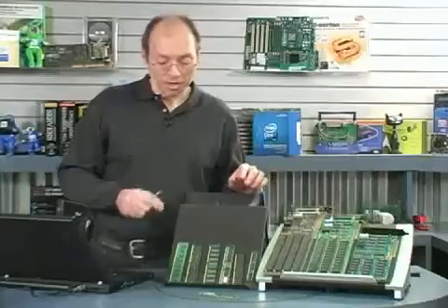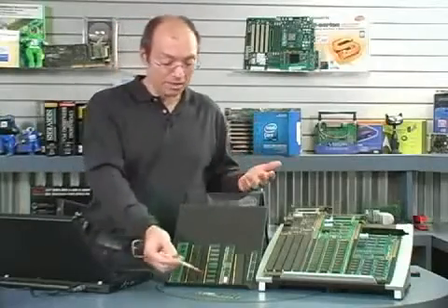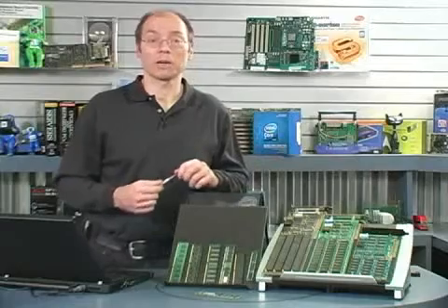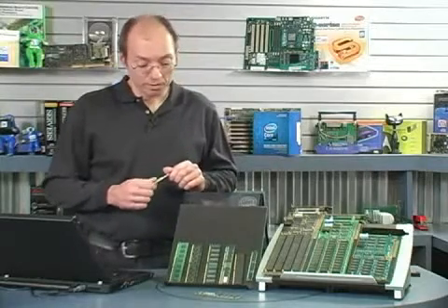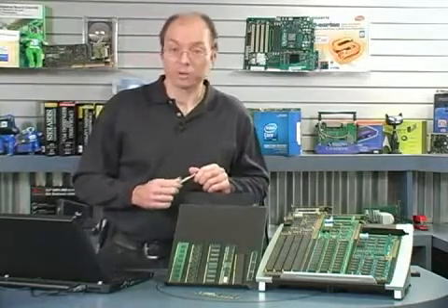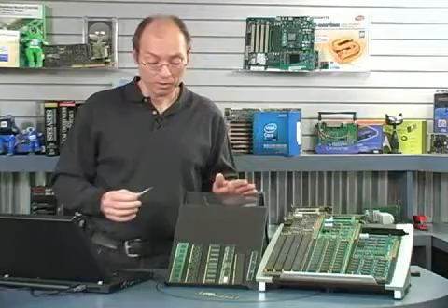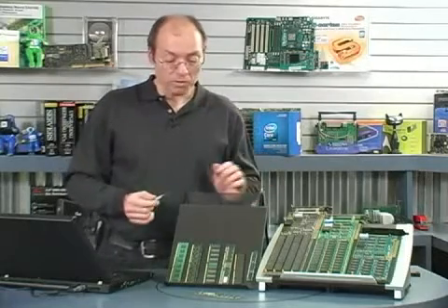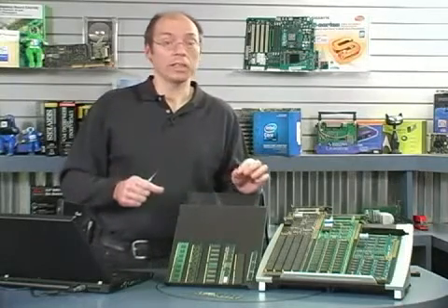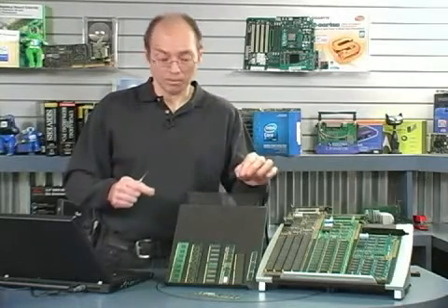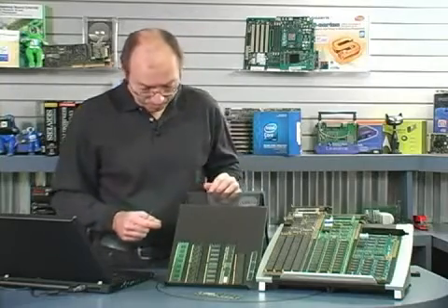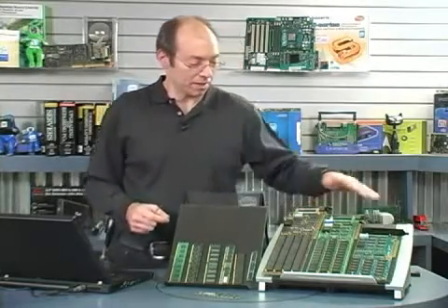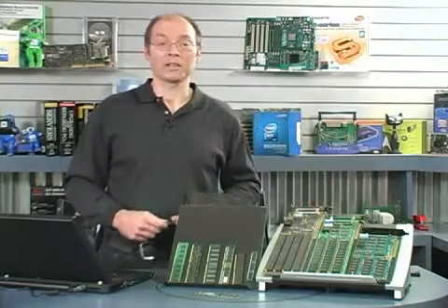So by altering the position of these notches, these keyways, they try to make sure that you can't plug it in backwards. But even with notches like this, I still come across burnt memory pins fairly frequently when people try to install memory and they don't know exactly what they're doing. So in any case, when you are installing memory, take care to make sure it's fully inserted in the socket and that it's in the right orientation. Well, I hope you've enjoyed this look at PC memory types and technologies throughout the years.